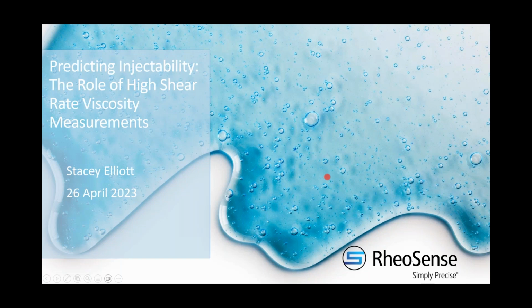Looking at this, we know we're going to have a pressure drop that occurs as we get fluid motion up and running. That force on the piston is going to be that pressure drop across the whole flow path times the cross-sectional area of the piston. This pressure drop has different components because we have different components in series: the barrel, what I'm calling a transition zone, and a needle. So it's just something that we add up: pressure drop across the barrel, transition, and the needle.